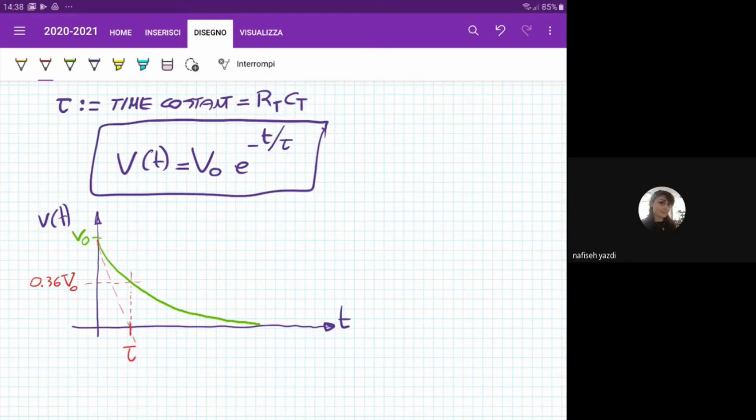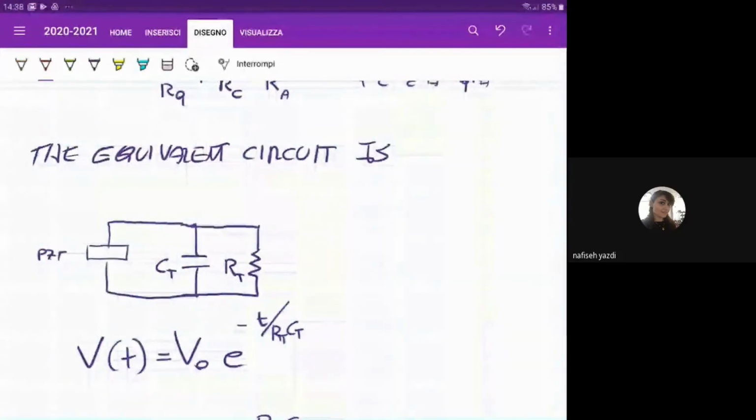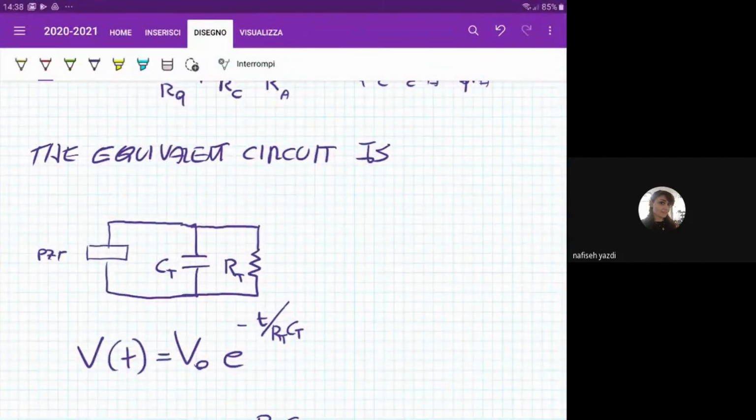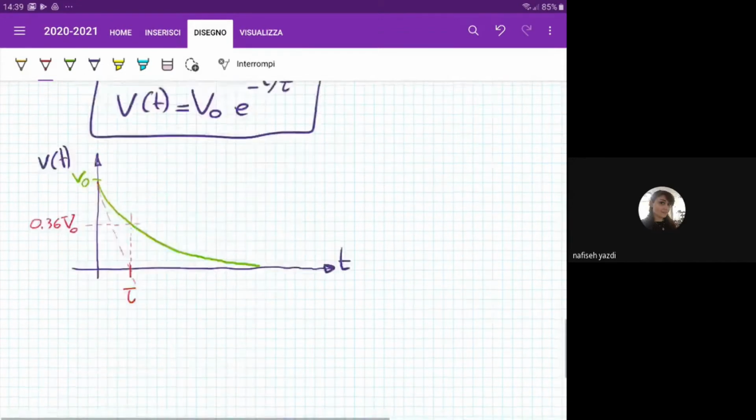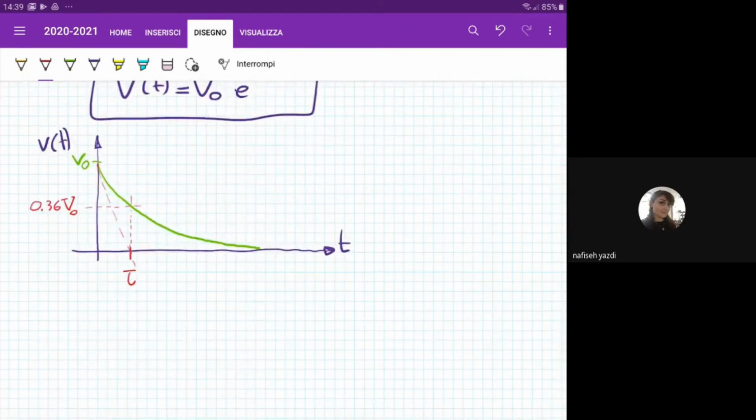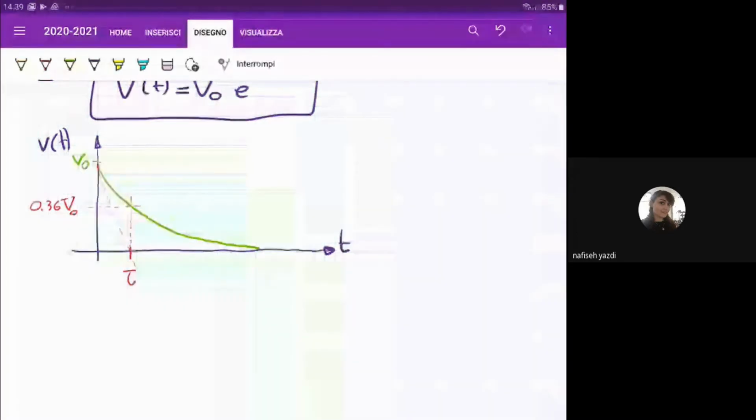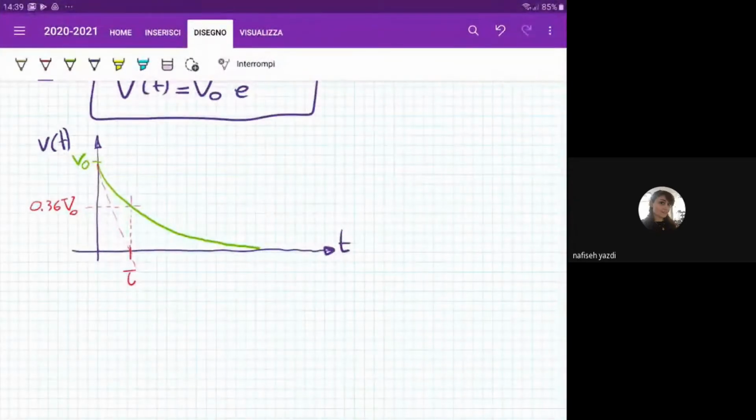So what does it mean then? It means that if your acceleration is characterized by a time evolution that is slow enough, or if you want, in reverse, if your measuring circuit is characterized by a time constant long enough, then you can have a measured quantity, the output potential V, that is quite representative of the time evolution of your acceleration.